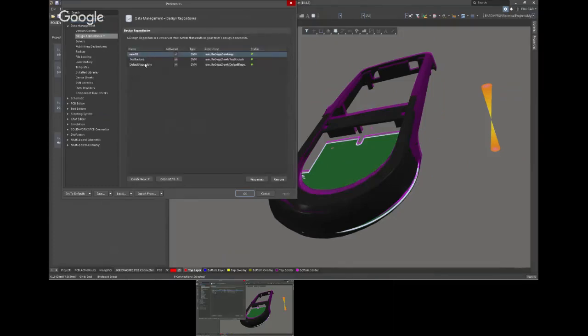That default repository is the one that's automatic. Remember I said there's that back-end intelligence system called SolidWorks PCB Services that keeps the data linked between SolidWorks Mechanical and Ultimate Designer. It has nothing to do with PDM. This is simply that managed project that you see. This is how we keep the data. Because it has a built-in version control system, it automatically comes with a default repository. If you have an existing repository where you keep all your files, we can connect to it by adding it to our SolidWorks PCB Services.